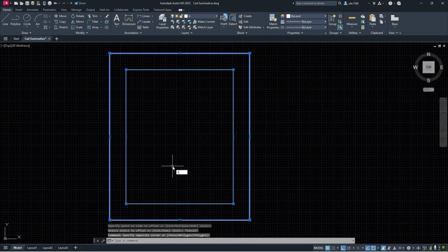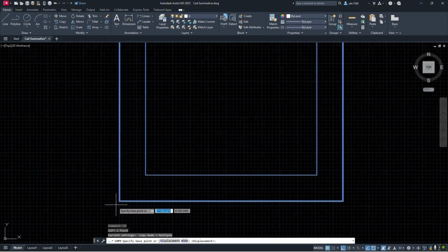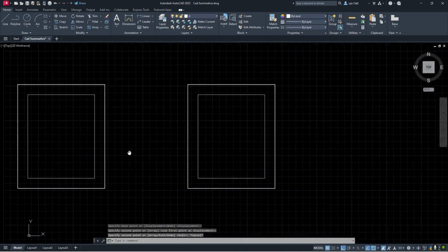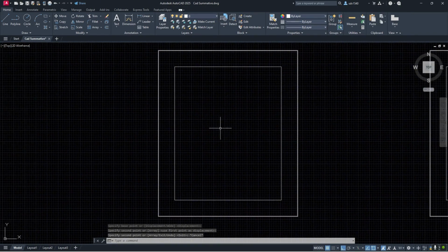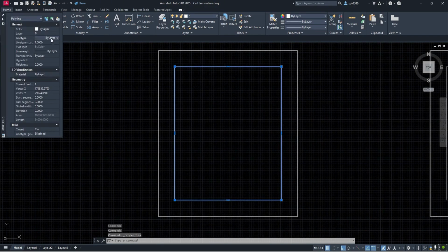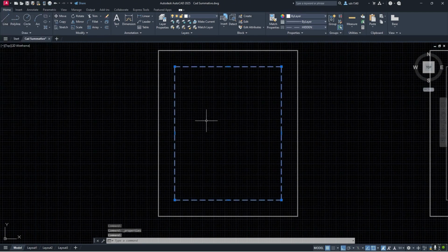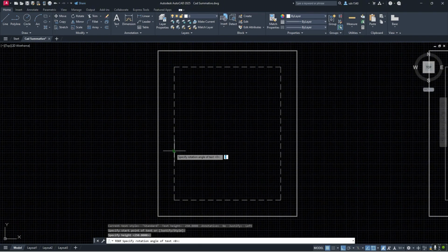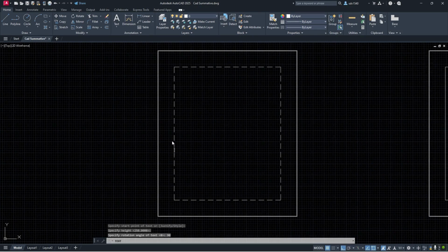Before moving on, let's create another copy of the array we have built so far. One will serve as our roof plan and the other will serve as the ground floor plan. Starting with our roof plan, we can set the line type of the inner rectangle to hidden to indicate that the rectangle marks the boundaries of the wall below. We will also add text on both sides that says this.